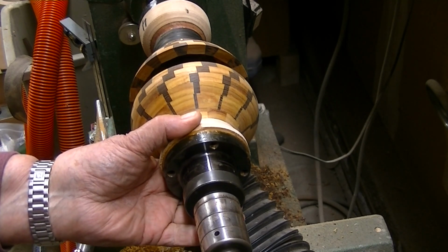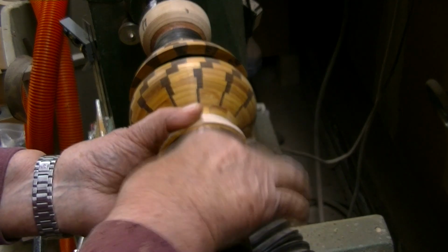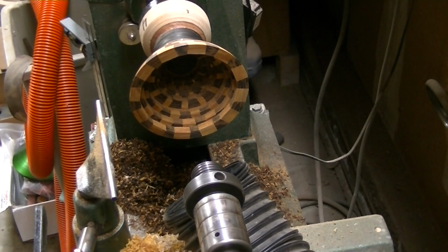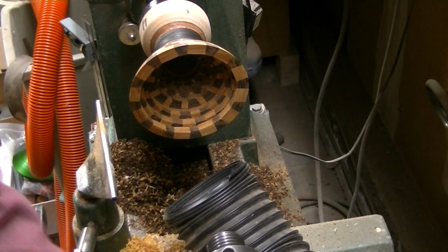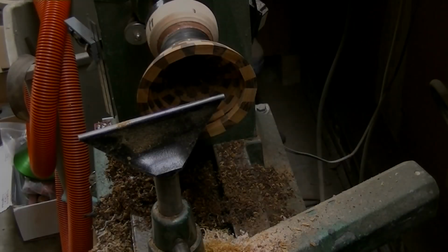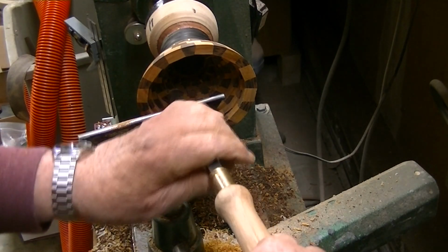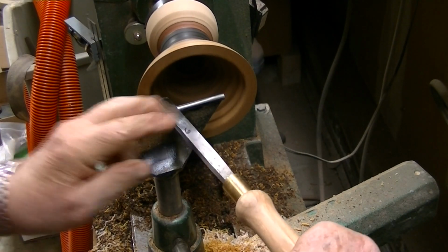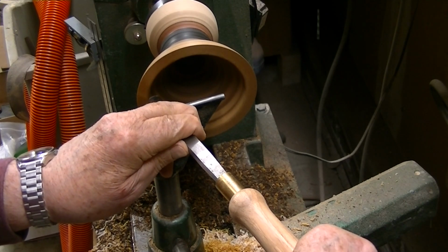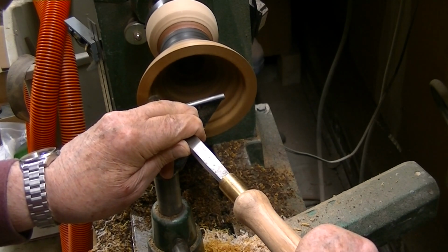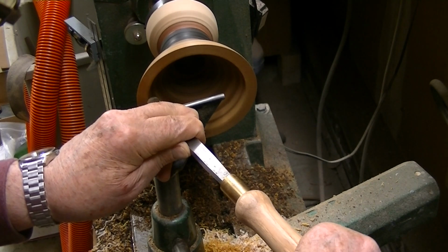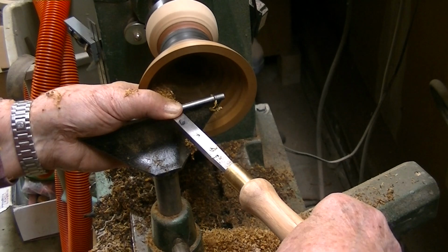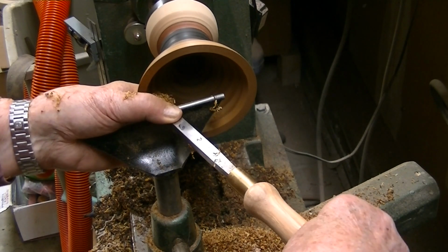So I'm going to remove the headstock, the head portion of this vessel, which is really on the tailstock. This gives me access to the piece that's ready to be turned. So this is the base of the vessel, and I decided to use a series of scrapers to take off the interior. This is a handmade, homemade, standard negative rake scraper. In other words, very slight curve on the face of it. And I'm making some really light cuts here just to get these interior corners cleaned up.